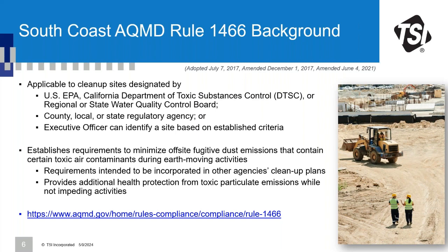What the rule does is it establishes requirements to minimize off-site fugitive dust emissions that contain certain toxic air contaminants during the earth-moving activities. So the rule is triggered when there's an excavation, remediation, some type of cleanup, that the soils are moving and generating dust or aerosols that could then leave the site and go into the community.